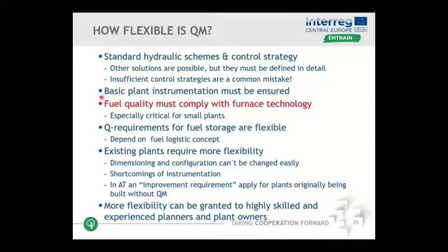Another thing which allows not too much flexibility is the fuel quality. It's very important that the fuel quality fits the furnace technology. Otherwise, you run into the first problems if you start up your plant. This is very clear. We see this later on. This is closely related to dimensioning of boilers, of the whole plant, of choosing the setup, and this has to fit together. The Q requirements for the fuel storage are very flexible from my point of view. There is a strict definition, but it really depends on the fuel logistic concept.